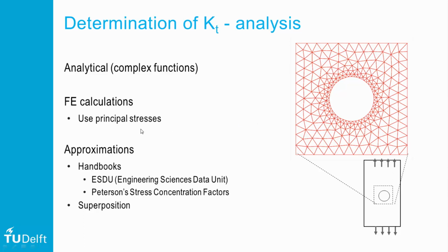Last but not least, because fatigue generally implies crack initiation and propagation perpendicular to principal stresses, it is highly recommended to determine stress concentration factors using these stresses rather than, for example, von Mises stresses. In all cases, comparison with approximations or handbook solutions is strongly advised. If no comparative cases are at hand, one may compare to approximations using the earlier discussed superposition principles.